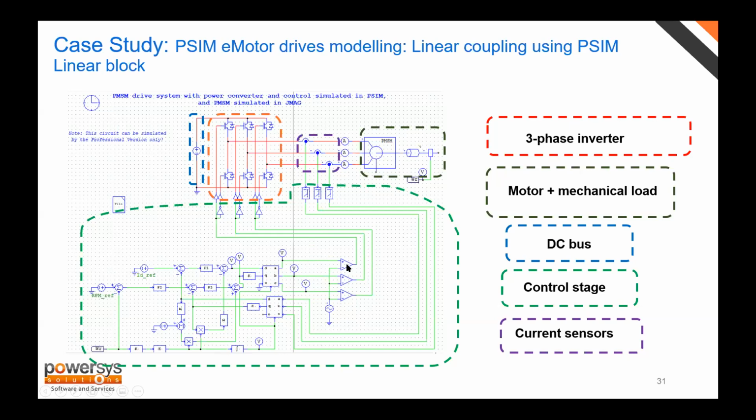Then we will have PWM signals which will directly turn on or turn off the IGBTs. So this is basic. And here we will get the speed and we will integrate the speed in order to get the theta value, the displacement of your motor.